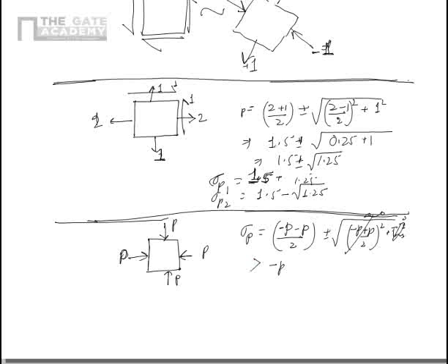So you see, that is the reason why we say that when there is a pressure, the pressure transforms into a pressure itself, which means that in case of a fluid, the pressure is equal everywhere. Throughout the planar element, pressure will be equal, which means that if you transform this element to like this, it will still have this condition only, pressure from all directions. So this is also an important condition to see, wherein both the applied loads are equal and in the same direction. Then the transformation doesn't change anything, which means it always transforms the element to itself, which means the stress state doesn't change at all. There will be no induced shear stress and there will be no change in the value of principal stress. Principal stress will be equal to the applied stress only.